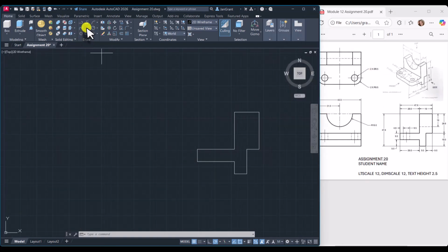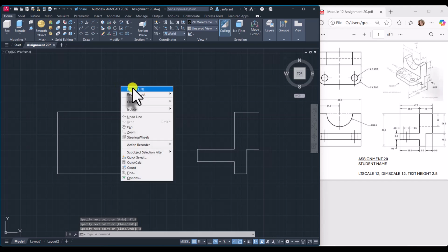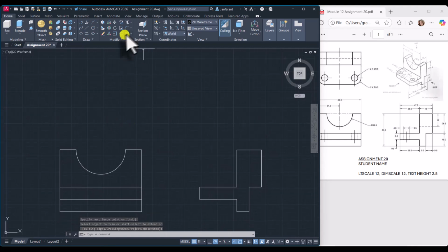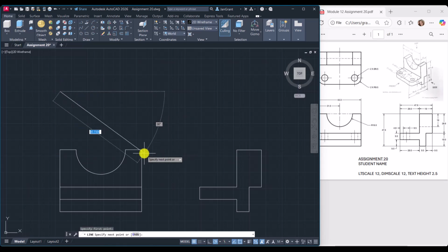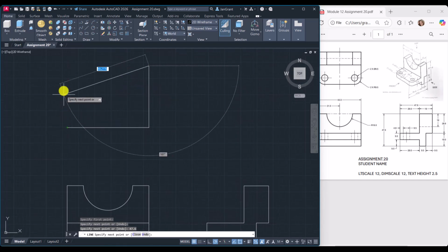So you see how I just followed the dimensions around to create that one, and then I tracked over to the other one. I could have tracked for that height. I probably should have. But you can see how I'm tracking all of these different lines over because they're all pretty much the same view, using my midpoint object snap to draw that circle and trim that out, and then using tracking again to track up and over the amount.